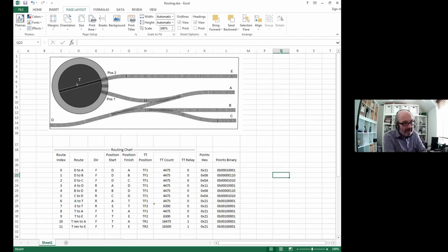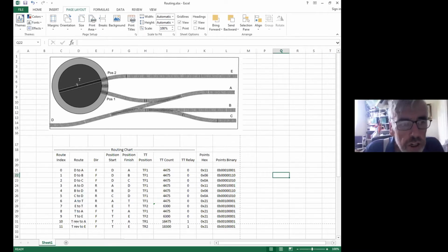That would be a more generic solution, but it's a question of getting the information, powering it, and getting the information back. But you don't need to. Why not just put the electronics in? Well, okay, it's N gauge, but where we looked at this in the past, you mounted the controls in the turntable itself. You have a DC feed, and then you can just use a relay to depower the track to stop the loco. So you could isolate the controls in the turntable rather than having to get them out through a slip ring. Yeah, it could do. Yes.